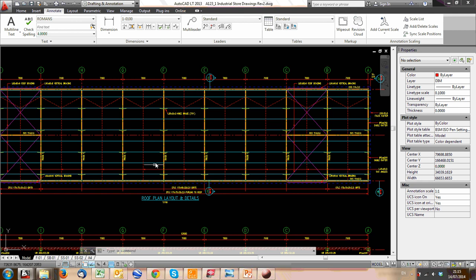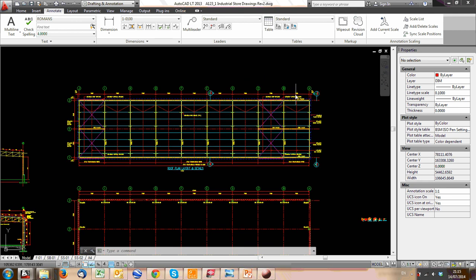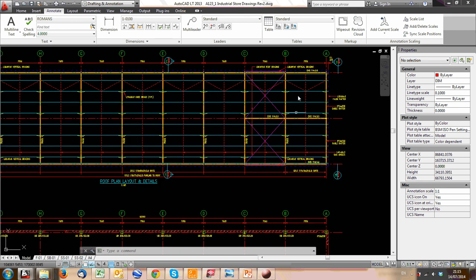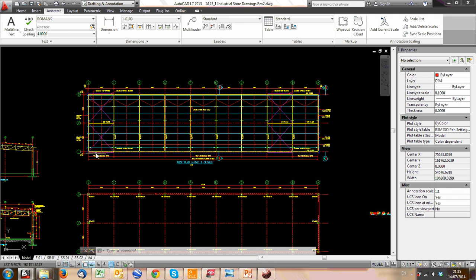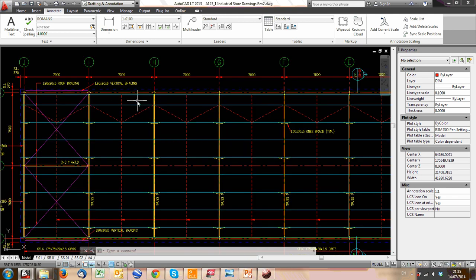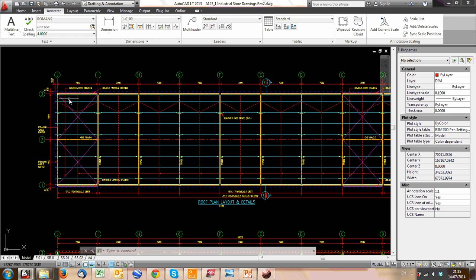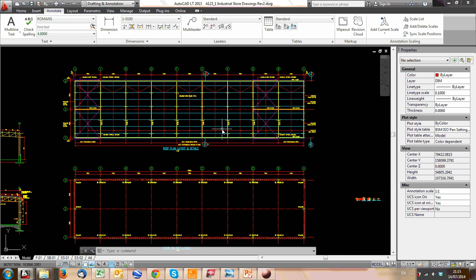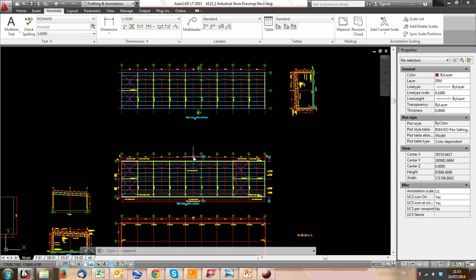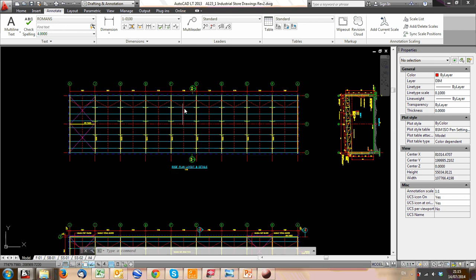Sometimes you'll have more sizes, sometimes you'll have less. It depends. With the new wind loading code, you generally have higher forces around the edges of your building, and then the first few meters, depending on the size of the building. So you might have heavier purlins for the first few, or you have them just closer spaced together to compensate for that. Right, and now that takes us through a full layout.